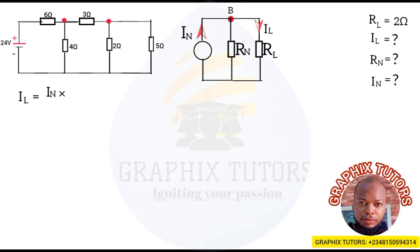And what is the current not flowing through? It's not flowing through RN. So I'll multiply it by RN, all over the addition of the two resistors, that is the Norton resistance and the load resistance, which is the investigating load. I'll term that equation 1.